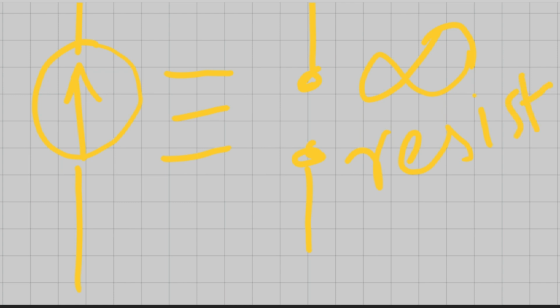In the superposition theorem itself, it has been written that the other sources are made inoperative by replacing them by their internal resistance. So this is the reason we replace the voltage source and the current source with a short circuit and an open circuit respectively. I hope you have understood till now. So let's start with a numerical, then your concept will be more clear.